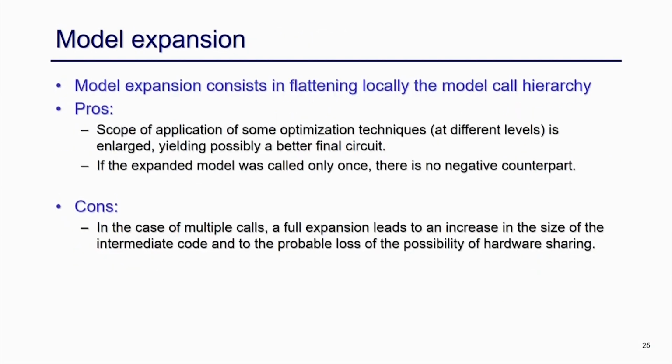If you remember when I was talking about the coding style, what I discussed is that whenever there is a function, it will create a module in the hardware, right, and if that function is called in multiple places, I am going to reuse that particular module if they are non overlapping, right, if their schedules are non overlapping.